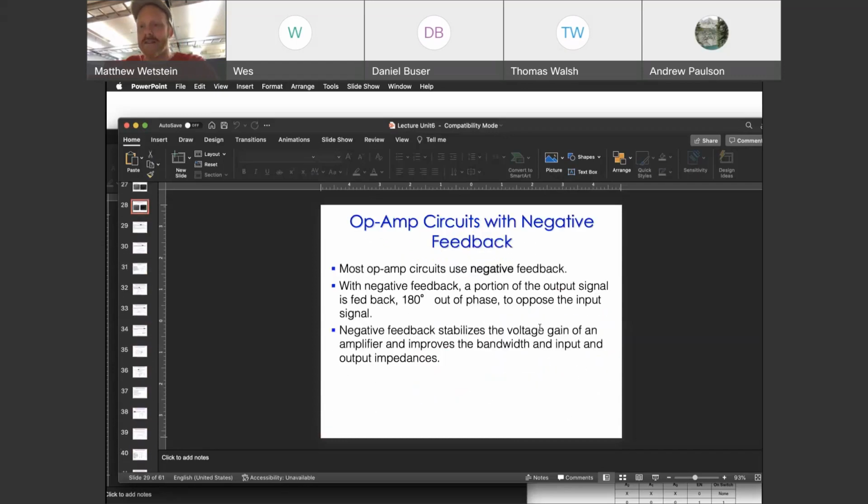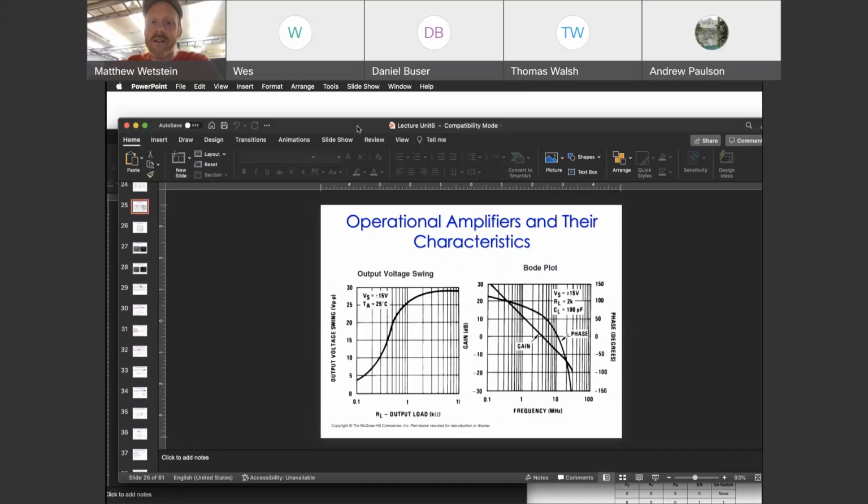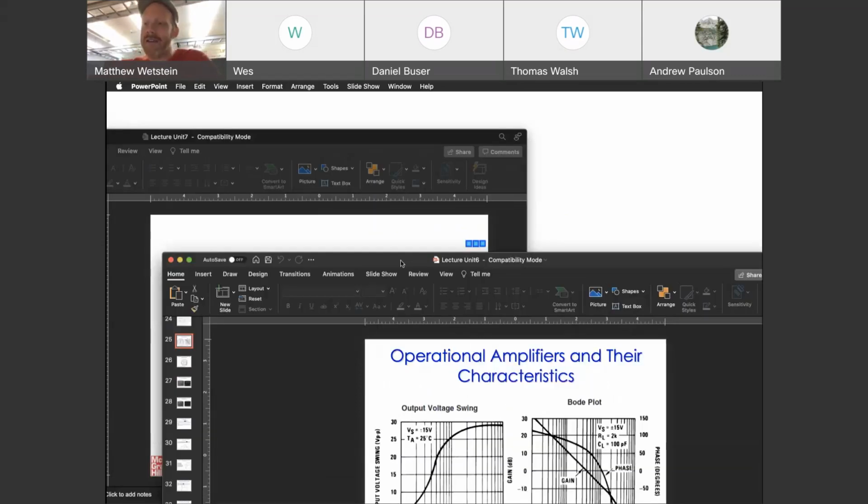But all those things I just said, and again with digital, at least be able to do truth tables and recognize the logical primitives. And of course, be aware that those logical primitives themselves are not electronic components. They are effective logical components that take high and low voltages and output a high or low voltage according to some convention. They're made by an assemblage of transistors and diodes.